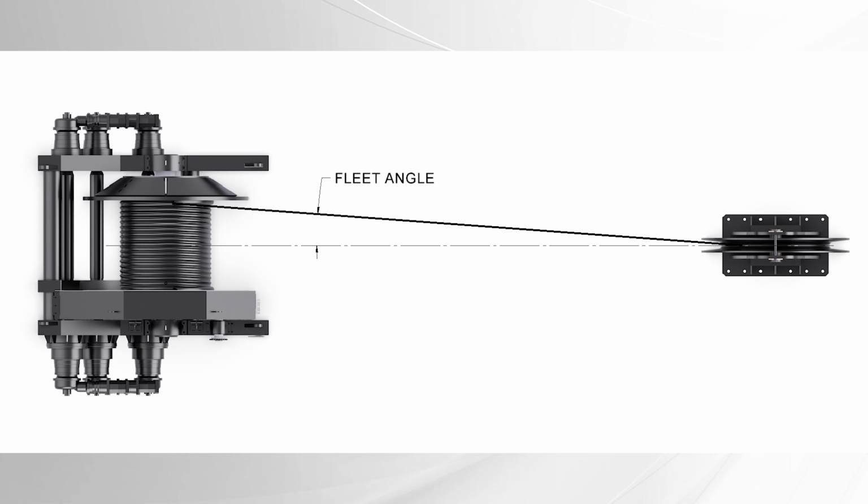The fleet angle is defined as the largest angle of the rope between the first sheave and the drum flange, relative to the center line of the drum. The largest fleet angle must now follow a recognized design standard.